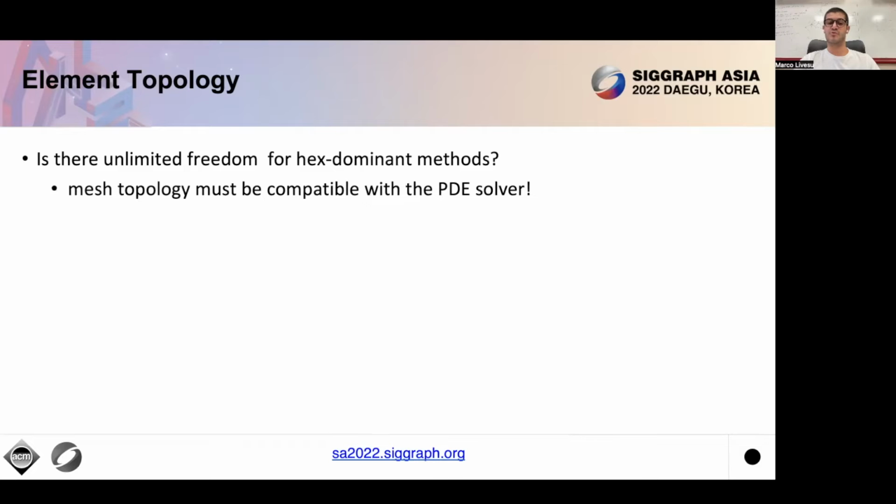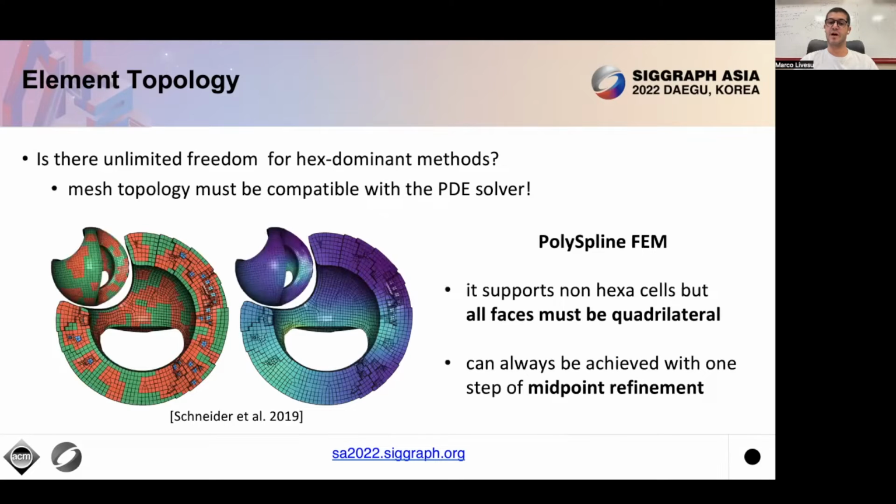And in reality, the answer is no, because the mesh topology must be compatible with the PDE solver that we intend to use to solve the PDE on the mesh domain. There are many different examples. Here I'm going to mention just one, which is related to the polyspline method proposed by Schneider et al. in 2019. And this specific PDE solver supports non-hexahedral cells only if all faces of the cells are quadrilateral faces. And in the paper, they describe, for example, a procedure that through midpoint refinement is able to always fulfill this requirement, at the cost, of course, of increasing the resolution of the mesh due to the refinement step that is